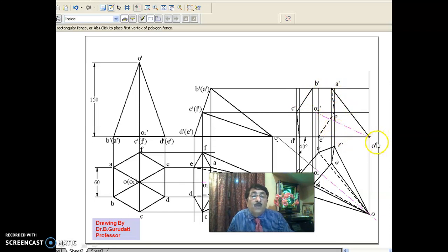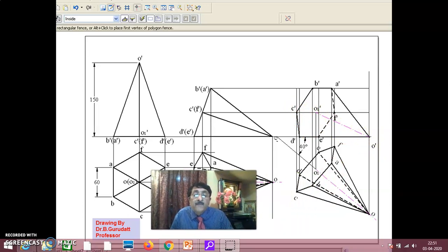Okay, you are now left with O'F', O'C', O'B'. Three more edges have to be drawn. Now you see O'C' is the C, as you see here, OC is the nearest edge which you can darken. OB is also a comparatively nearer corner edge, that also you can darken.